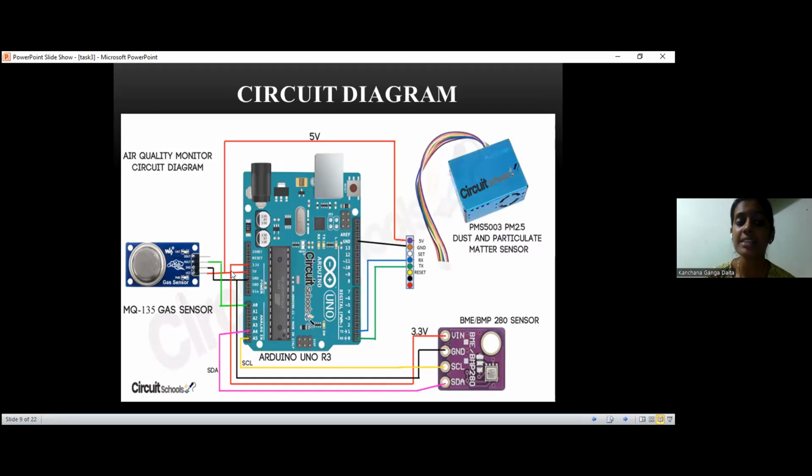Or else, if even that 5% is crossed, whether it is a lesser case or a greater case, it gives a digital output. For that we use particular signal conditioners, in which the signal can be transformed into the required output, digital or analog, from the output of these MQ135 sensors.